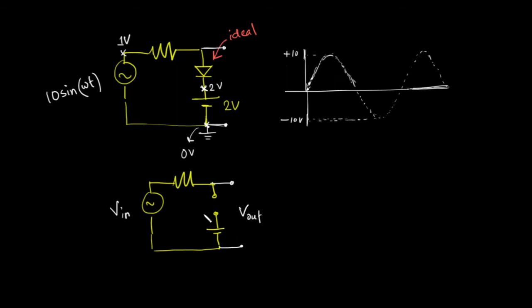Can you tell? Suppose I have a voltage source and a resistor and an open circuit at the front, and I connect a voltmeter to this open circuit. What voltage will I see? I will see exactly the same voltage as the input.